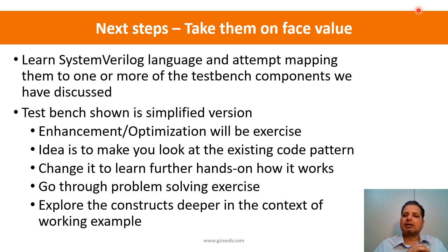To learn to read code, you should have this structure of the test bench that has been taught to you in the back of your mind, and at any point in time you should be able to map it. Where are the generators, where are the translators, where is the scoreboard, where are the drivers, where are the monitors? You should be able to ask those questions and look for those answers. That is the whole idea of this exercise.